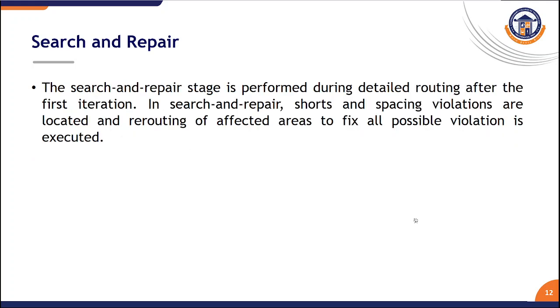So the last one is search and repair. In this stage, the routing violations are fixed. This stage will resolve shorts, open circuit problems, DRC violations, and timing issues. This step ensures the design is clean and sign-off ready.